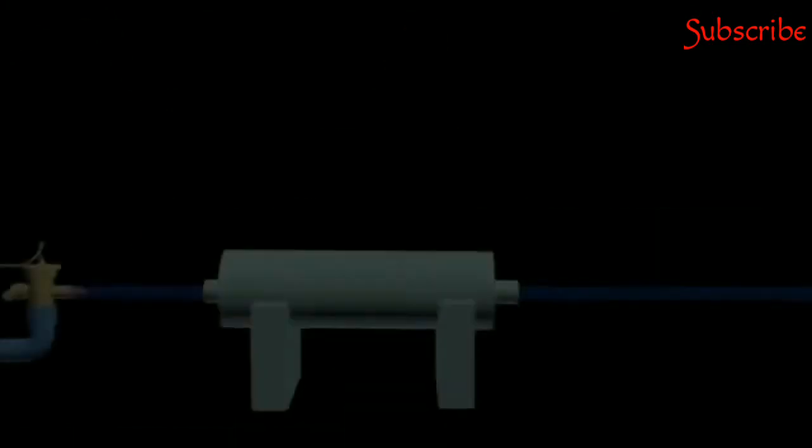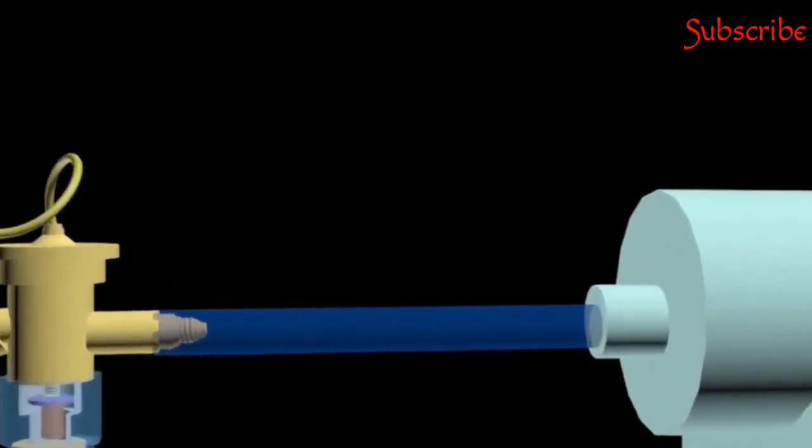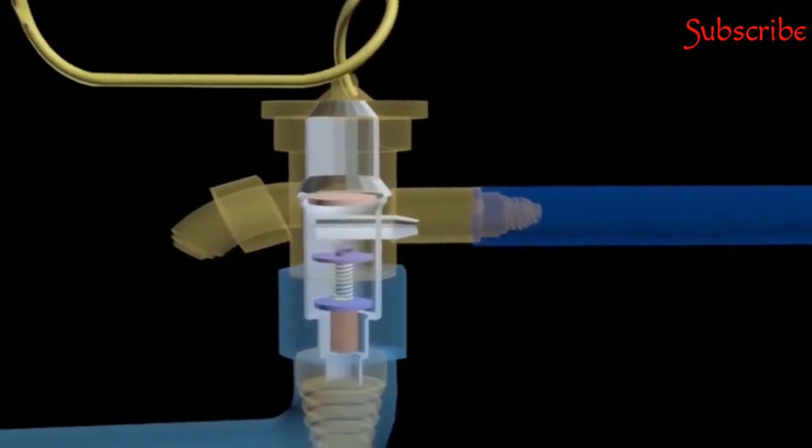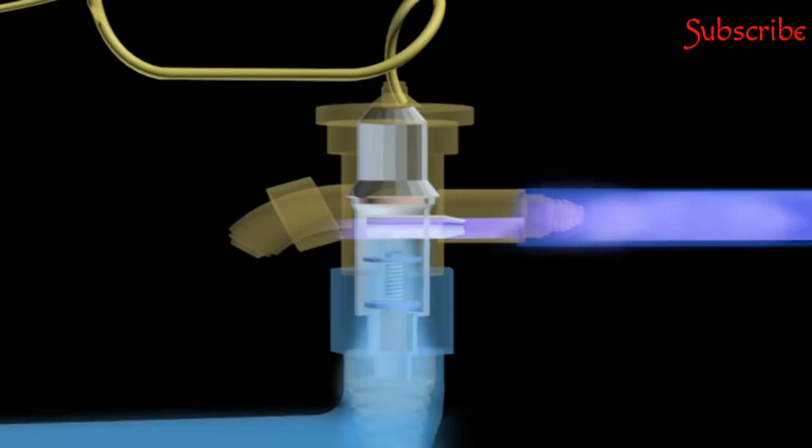Expansion valve. Expansion valve serves to reduce the pressure and control the flow of refrigerant going into the evaporator. When the pressure of the refrigerant has declined drastically, the temperature will drop dramatically, which is lower than the chilled water temperature.